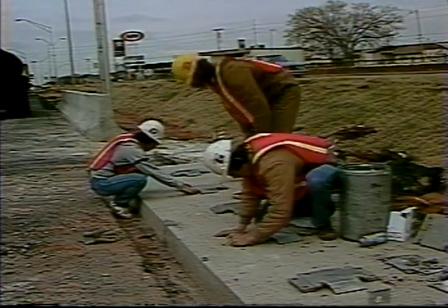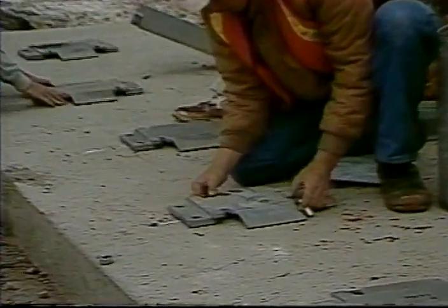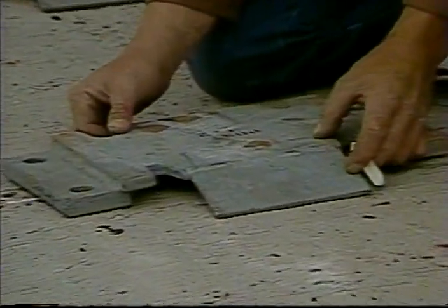The slip bases for posts 1 and 2 have flared slots, while the slip bases for posts 3, 4, and 5 have straight slots. Arrange the bases next to the proper post locations with ramp ends touching the ground before proceeding to the anchoring process.